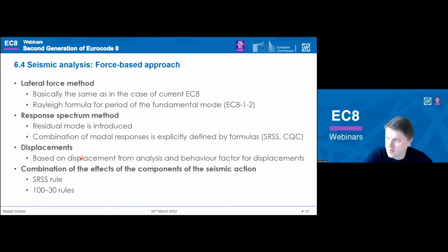So we no longer have the simplified coefficient-based formulas for defining the period of the structure, but the Rayleigh formula for the period of the fundamental mode is introduced. It's not completely the Rayleigh formula because it considers only the force at the top of the structure in one direction and at one level, but basically it provides the same results. So this is a novelty and an improvement in comparison to the current code.